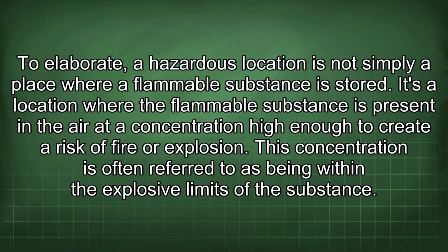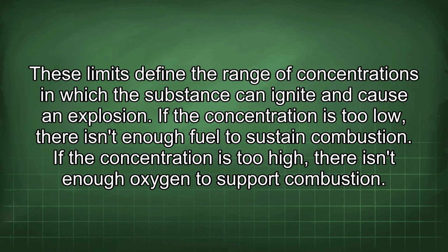To elaborate, a hazardous location is not simply a place where a flammable substance is stored. It's a location where the flammable substance is present in the air at a concentration high enough to create a risk of fire or explosion. This concentration is often referred to as being within the explosive limits of the substance. These limits define the range of concentrations in which the substance can ignite and cause an explosion.